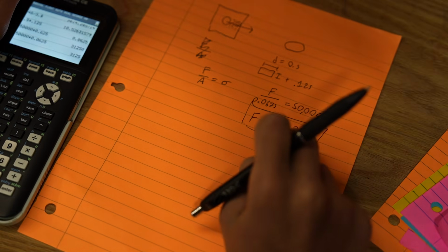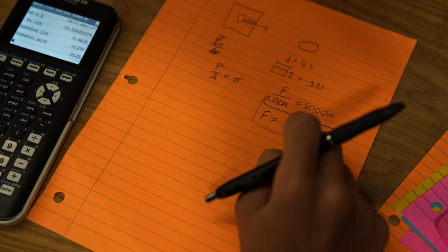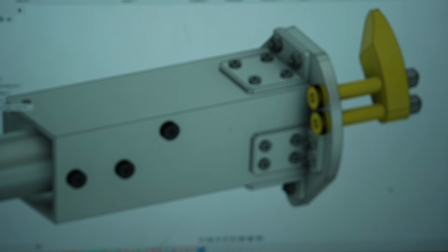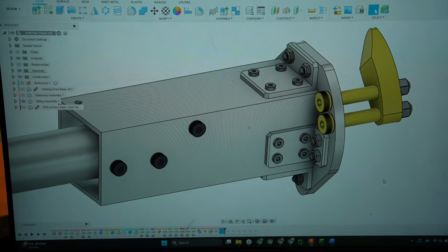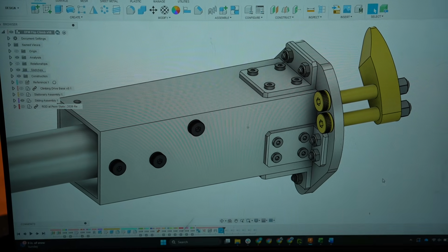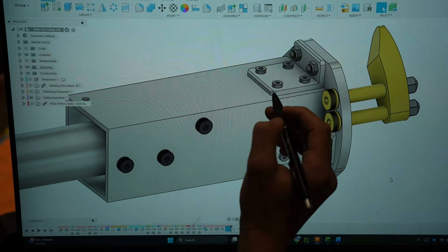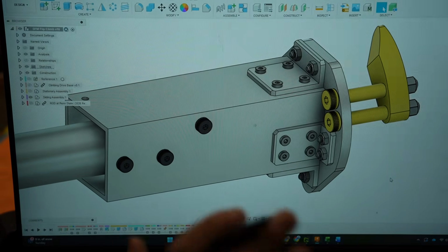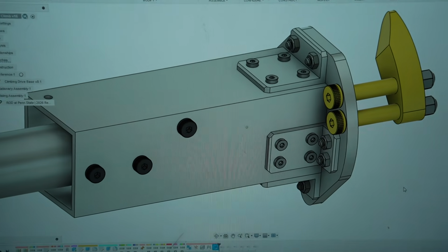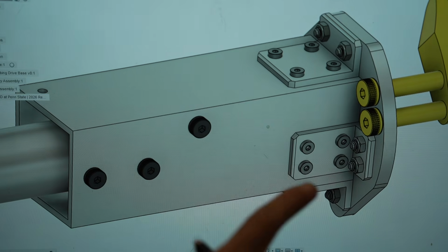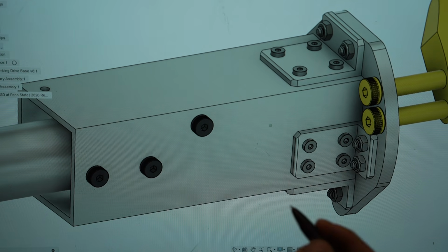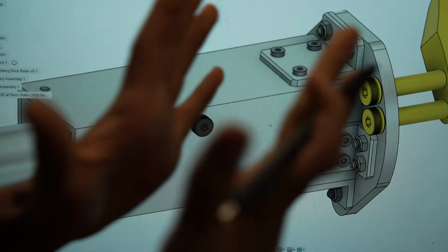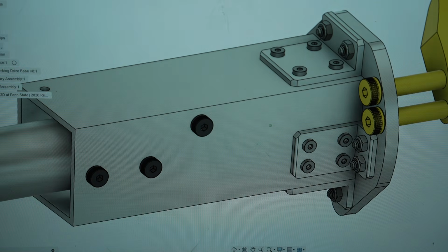So we did this math on, if we can look at the CAD again. Yeah, to be clear, this is bearing failure, so ovalization. Tear out, you can do shear in the walls that would tear out. My apologies. They are slightly different in a subtle way. But tear out should be using the side profile length. We're not going to get into that. But that's why you shouldn't put holes close to edges, because you really become at risk of literally tearing out, losing material. Ovalization is when you just crush the walls around your fastener.